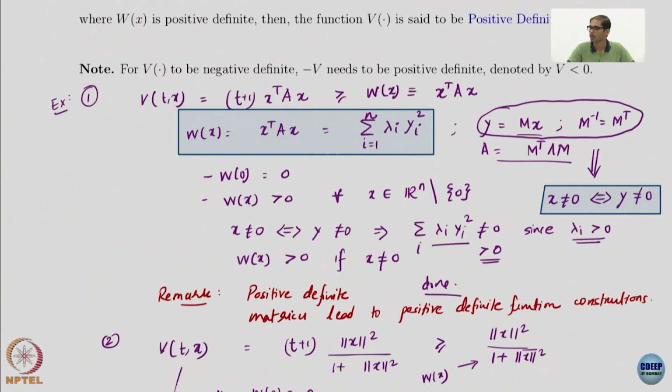We have not talked about this, obviously, we will come to this in the second half of the course, but a lot of systems, a lot of aeromechanical systems, can be linearized via feedback. And for most of those systems we can use quadratic Lyapunov functions, because once you have something linear appearing in your dynamics, then you can use the linear Lyapunov candidate, which is x transpose Ax or Px or whatever you want to call it.